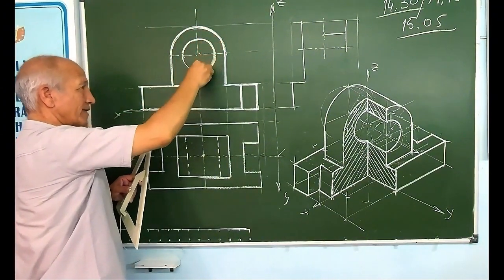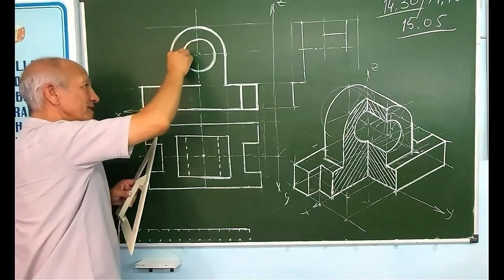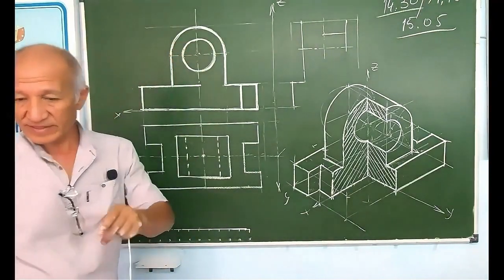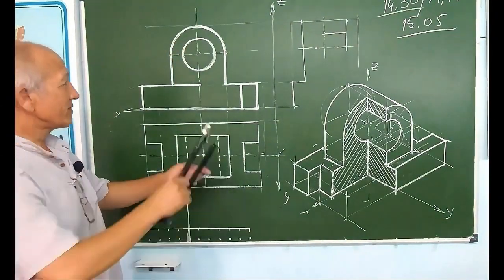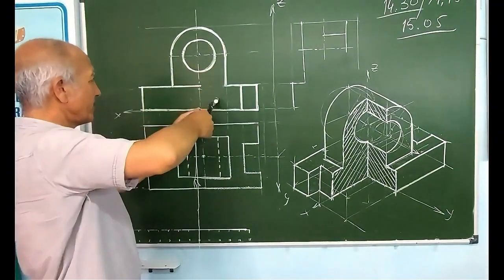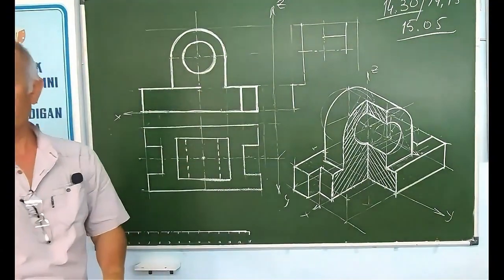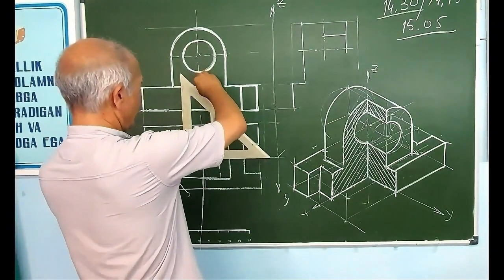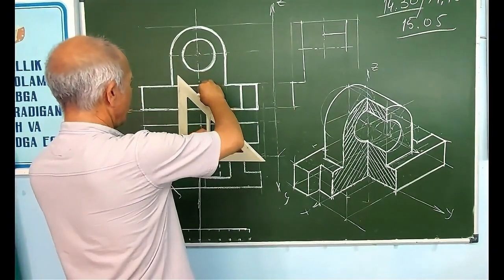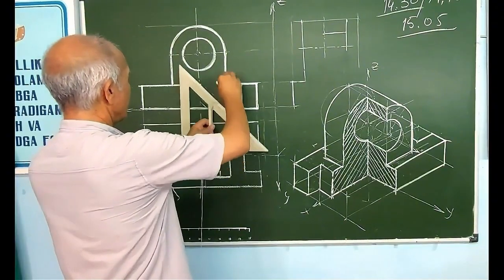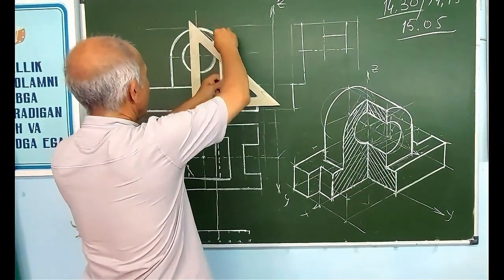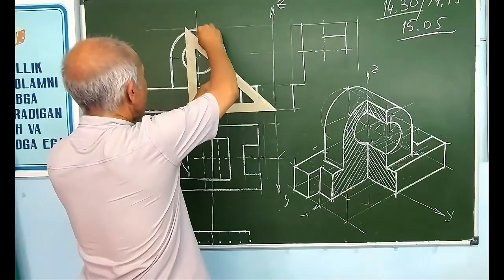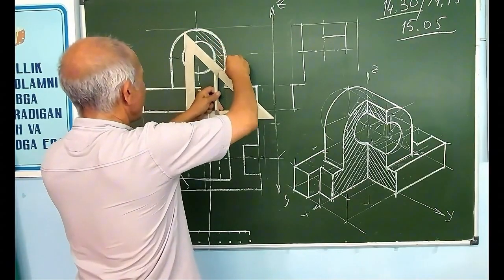There's the matter of hatching here. The hatching should be at 45 degrees. Here too, if you don't know what 45 is, I'm doing it like this, making them all the same, like this. This gives you 45. So this is 45, here you go. See, can you see this? There you go. So you shade this as well, like this. Now as we're shading, can you tell the thickness between this line and this line now?